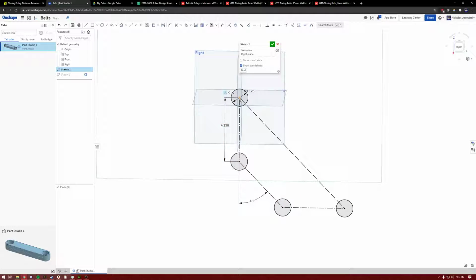So if these shafts were cantilevered, which you would often do with a belt run, you might run into issues, because they're going to pull towards each other, and it might result in things bending. So generally, I try to avoid this unless they're very well supported in aluminum. That's the kind of thing you use on an arm or some really robust mechanism that might benefit from that kind of control optimization. And usually in that case, you're probably just fine doing a dead center to center.